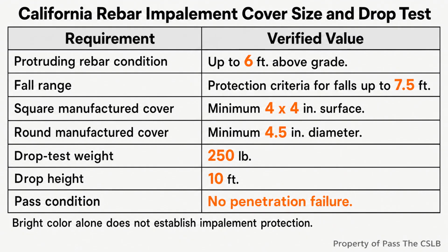For Masonry Grout, the boundary is the sampling trigger. Has the testing plan accounted for each mix design, each placement day, and the wall area frequency? For reinforcing steel, the boundary is worker exposure. Does the protective system meet the actual impalement criteria before anyone works above the bars? Notice that none of those questions ask the General B contractor to become the specialty installer. They ask the General B contractor to control sequencing, documentation, license participation, inspection readiness, and safety.